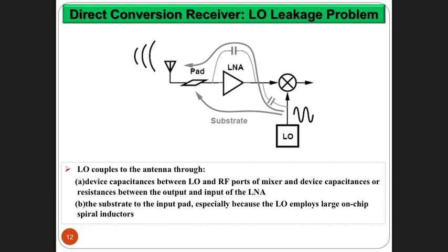What's bad about leaking back into myself? It damaged your signal amplitude. The leaking that comes out from here, it's just a carrier in the middle of my signal. What's the problem? I mean, there is the frequency deviations that happen from the local oscillator. Assume there is no deviation. It will add up with the signal. So when it adds up with the signal, what does it produce? The LNA saturates, because you're adding more.